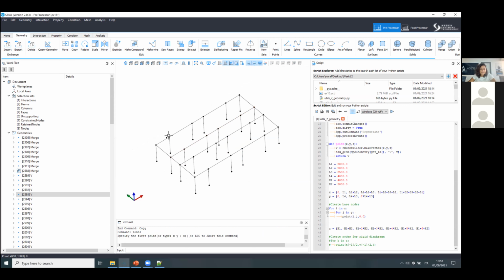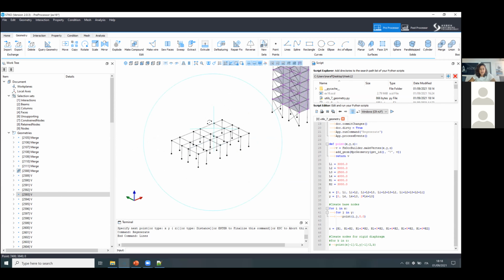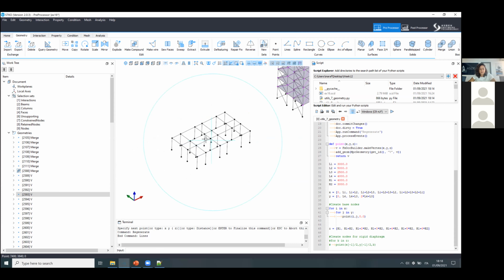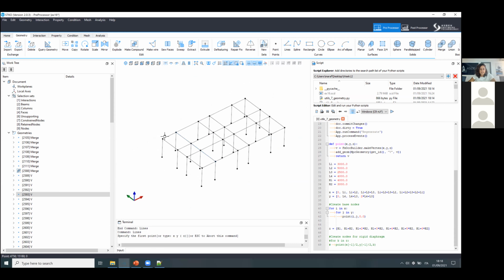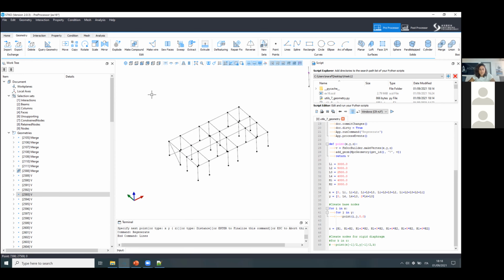This is because STKO works with a boundary representation geometry. So you don't have separate instances joined when they're created in the same place, but they get duplicated. So let's say that now I created my first level. If I go on and assign the braces to the side here, what changes if I use the merge command?